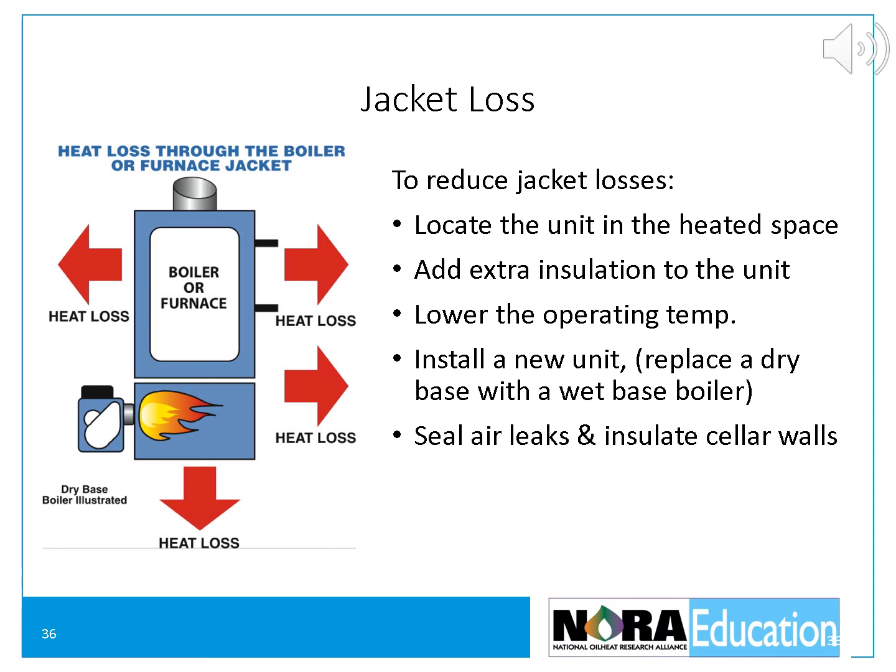Based upon Brookhaven National Lab testing, jacket losses from appliances can vary from less than 1% to more than 10%. This loss is highest while the burner is firing. Typical flame temperatures of approximately 2,000 degrees Fahrenheit drive heat through the chamber wall and then through the jacket. Dry base boilers that do not have water surrounding the combustion area tend to have higher jacket losses than wet base boilers where the water-backed heat exchanger extends around the combustion area to the floor.